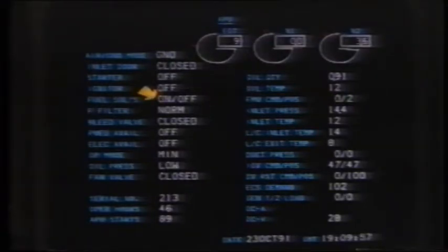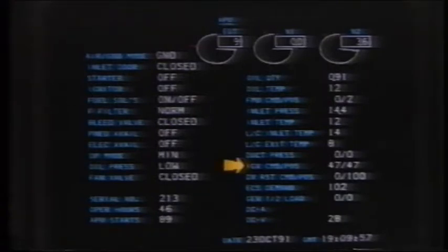The controller commands the air inlet door to open, then turns on the APU primary fuel solenoid and sets the inlet guide vanes to 47%. At this point, the controller is waiting for the APU air inlet door to open. When the inlet door is open, the controller turns on the starter and the igniters. Then it sets the fuel metering unit to 24 for starting, and it blanks the DC amps indication.